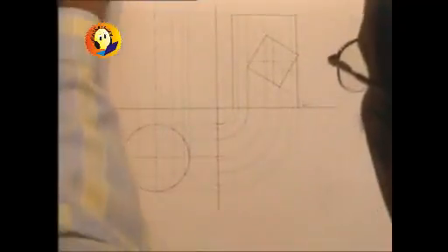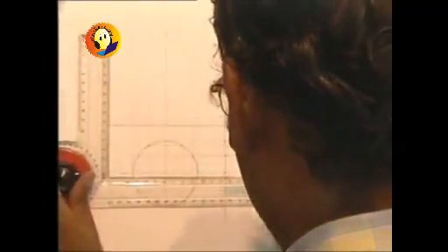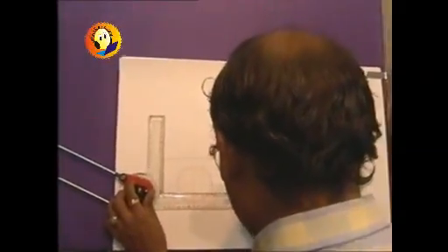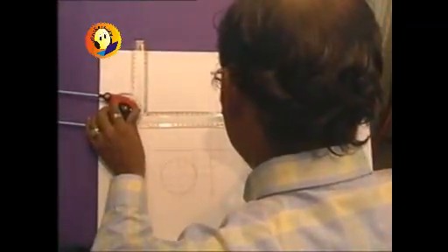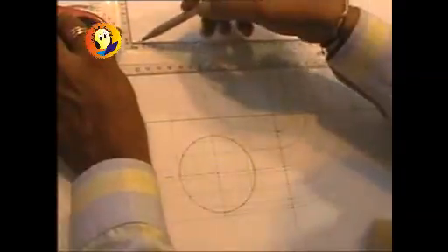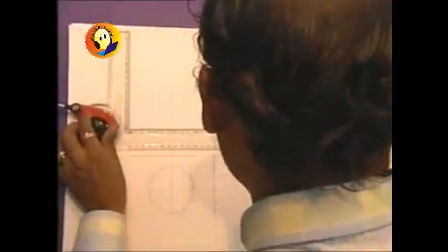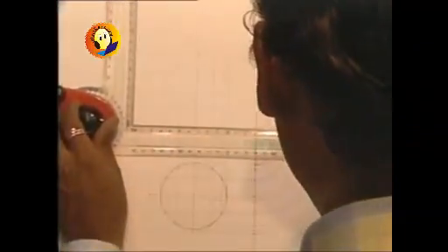And then in top view you are required to draw those generators parallel to XY. So you get those generators in the top view, and in the same manner you will be having those generators even in the front view. This time none of them is overlapping any other generator, and so all the 4 will be seen distinctly.